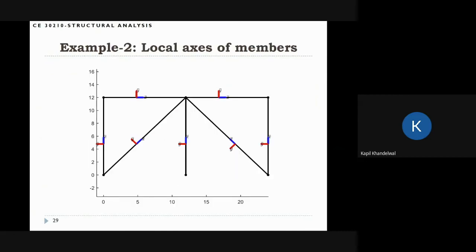So these are the orientations of these members. Again, orientations are necessary to define the member loads correctly, because the member loads are defined with respect to the local axis. So this is the local axis, and this is not changing. My definition remains the same. And there are no member loads on the bracings, because bracings only carry axial forces. So we should not apply a uniformly distributed load and things like that on the braces. That's not the usual practice.